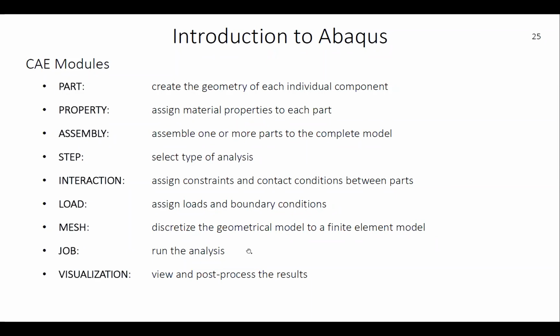For instance, if you have a too deformed mesh, that may cause problems when doing the numerical integration using the Gauss quadrature, as you may remember from the last lecture about having distorted elements and how that may affect the accuracy of the results. So you may have a lot of warnings, but you may still be able to run the analysis. It also gives you an error if something is defined in an inappropriate way, such that you cannot solve the system.